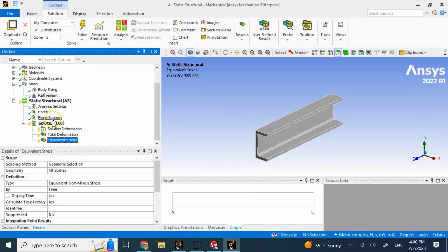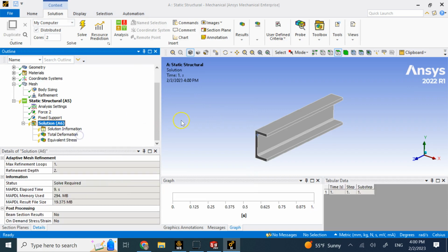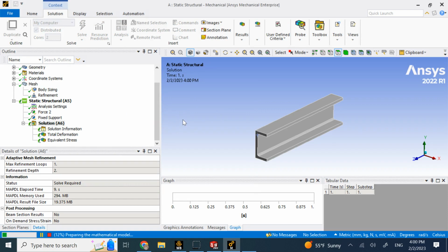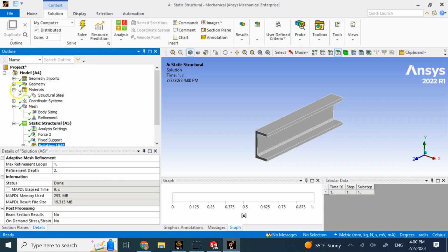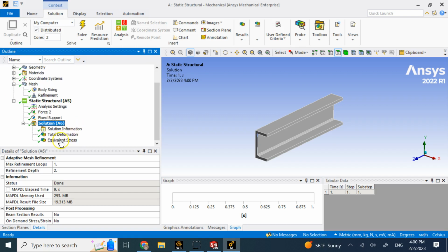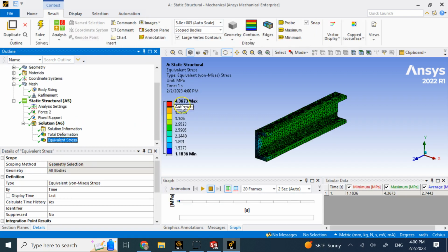What I want to show you is some other types of load other than force. But we want to make sure here we are staying within the linear region, and we are not going to go to the plastic deformations. So the yield strength for structural steel, which is the material right now, is 210 meg. As long as the maximum here is below that, which clearly it is way below, I am relatively safe. So it's nothing big.